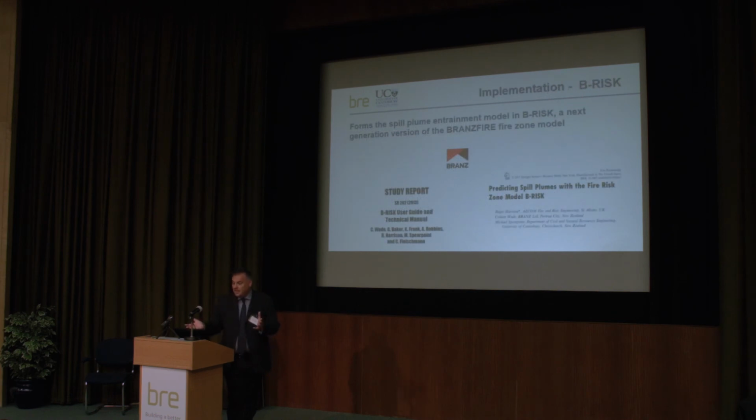Another area that we've included this is in BRANZ, the zone model BRANZFIRE. Some of you may have heard of this. More people may have heard of the zone model BRANZFIRE. So I was working with the engineers at the Building Research Association of New Zealand. They didn't used to have a spill plume model in their zone model. We've now included it in B-RISK, which is the next generation version of that. It's in the user guide, and then we produced a paper in Fire Technology, again peer-reviewed, to show validation of its use. So we have a simple form, we have it in zone models,